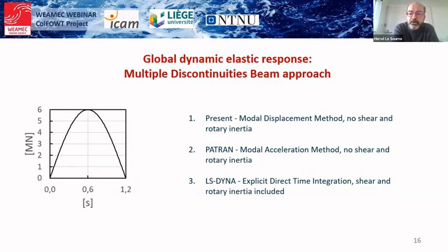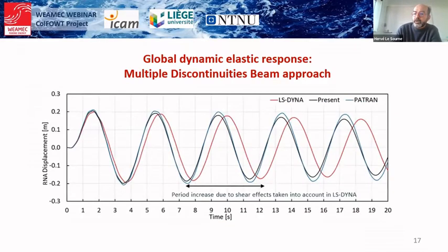The multiple discontinuity method was implemented in the ColFOWT project, and the displacement, velocity, and acceleration of the nacelle were compared to finite element results, obtained either by using a Patran and Nastran solver with a modal superposition approach on a beam model, but also with finite element results from LS-Dyna explicit simulations. And we can see here the time evolution of the displacement at the center of gravity of the nacelle.